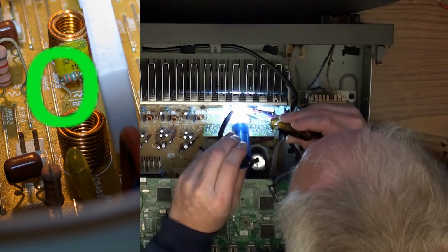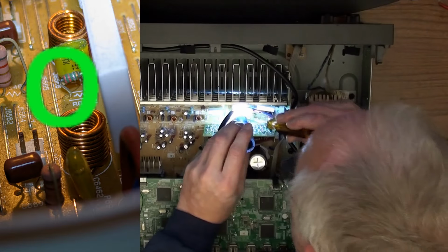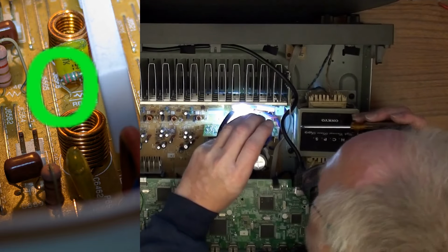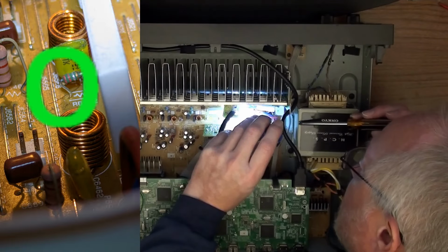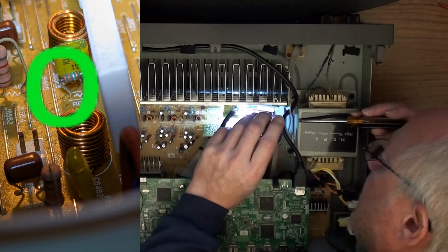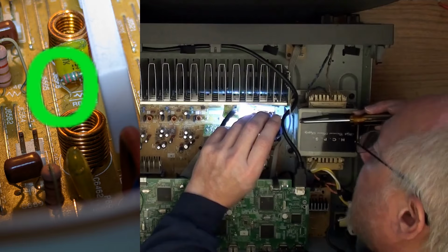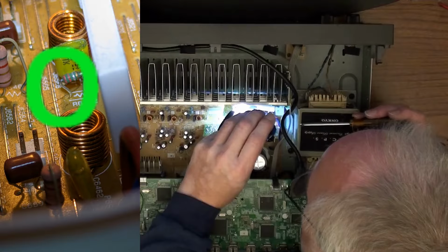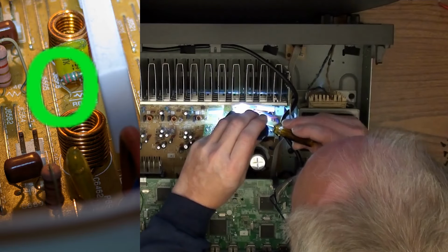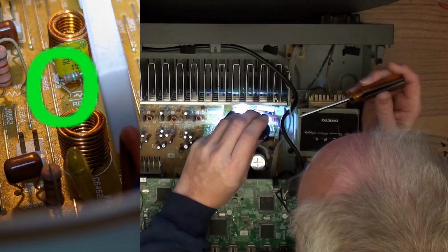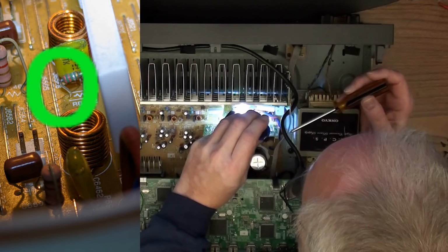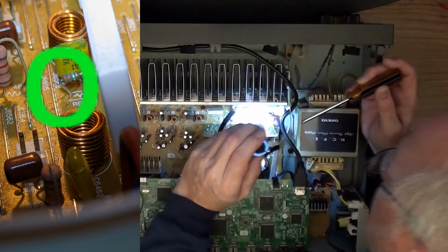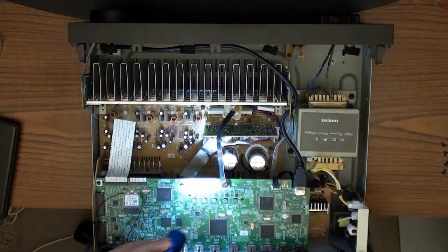And you can see in the picture that it is shorting between that little resistor and the yellow capacitor. So that too could be causing the problem, depending on if those are connected. And it's shorting across the jumper wire too. So it's shorting 3 things together right there. So all those things could be causing,